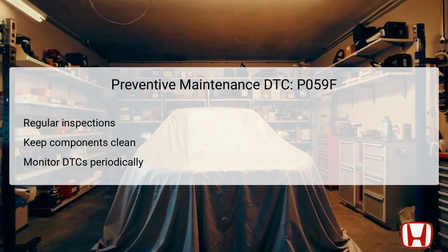Additionally, it's beneficial to monitor for any diagnostic trouble codes, DTCs, periodically using the Honda Diagnostic System. Early detection of any potential issues allows for timely repair, avoiding more significant problems in the future. Following a maintenance schedule as outlined in your owner's manual will contribute to the longevity and efficiency of the vehicle, ensuring the shutter grille system remains intact.